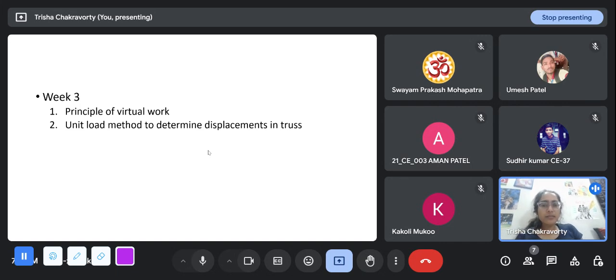But why we are concerned about the displacements or deflections is that a structure is built for a purpose, right? Imagine in a factory we have an equipment, maybe a tall crane, that we have to pass through a door, and the beam on top of the door, which is called a lintel beam, exceeds a certain displacement, and in that case the movement of the crane is hampered. Then though the structure has not collapsed, it is not serving the purpose for which it was built.